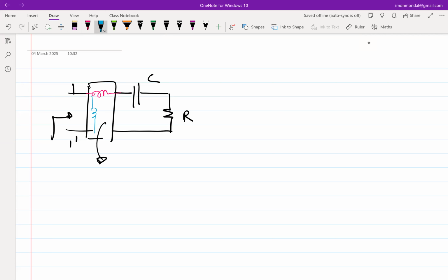So let's check the option which is the red guy, the series option. If I connect it like this, note that you'll have to resonate out the capacitor. If we resonate out the capacitor, the combination of L and C gives you how much impedance? 0. So looking from port 1 and 1 dash, you get resistance of R. So that also goes out of the window. So what is the only thing left? Parallel. So now I have nailed down the topology.